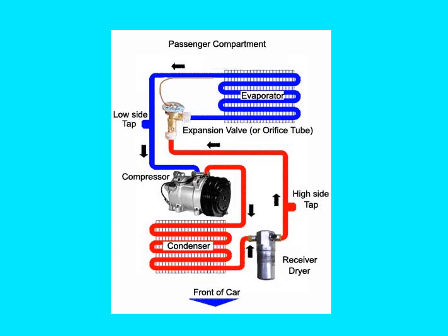So those are the major components: compressor, condenser, the receiver dryer, the expansion valve, and the evaporator. And then of course we'd have the lines that are connecting those components together. Now the AC system, nothing will exchange heat unless the compressor is engaged. So the compressor would be engaged with the AC being requested on. The compressor will be spinning, moving the pistons back and forth, and that's going to start the refrigerant to flow.